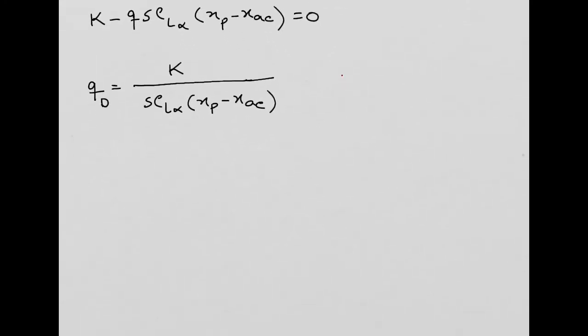The dynamic pressure is 1 over 2 times density times the square of velocity. I can then predict the maximum velocity my aircraft can fly before it gets into divergence, before it gets into that critical point where my angle theta becomes infinity and my lift also becomes infinity.